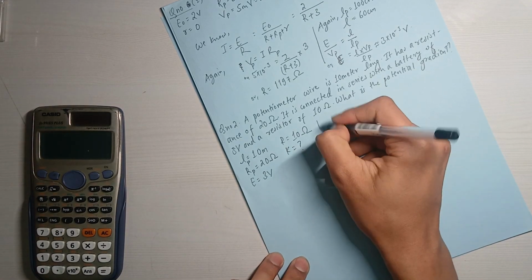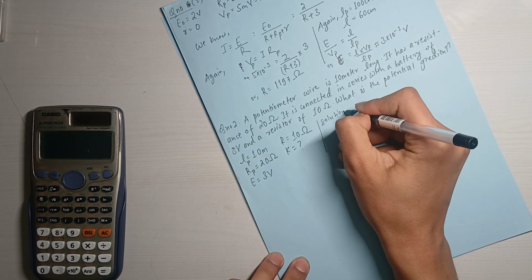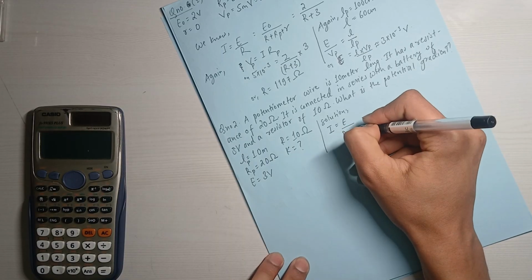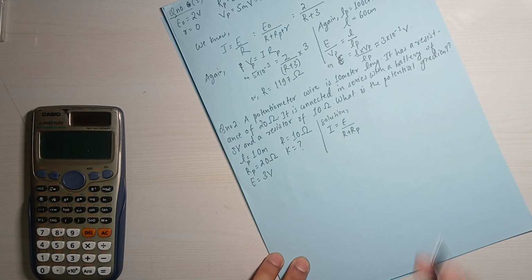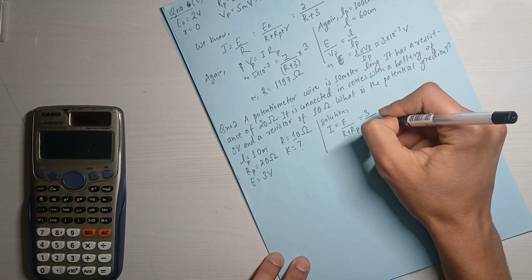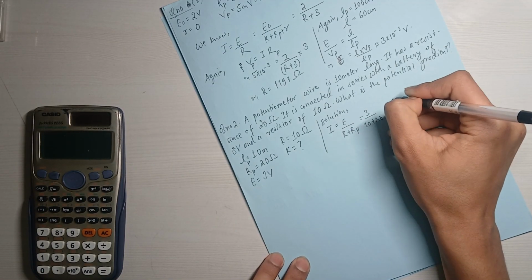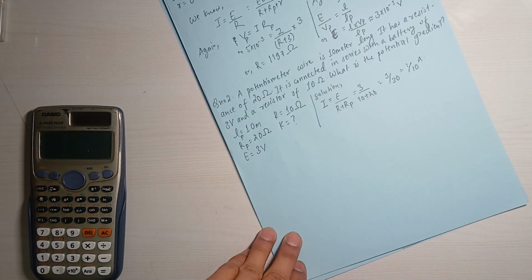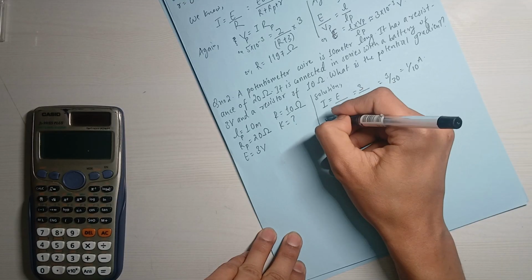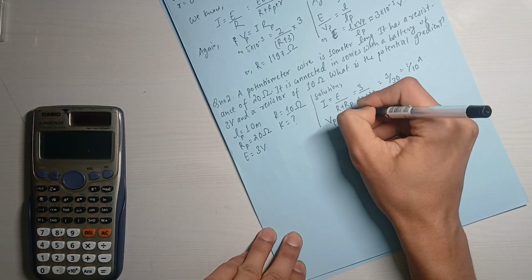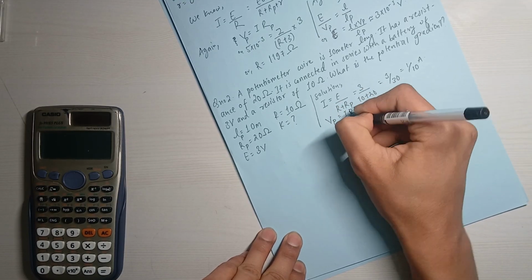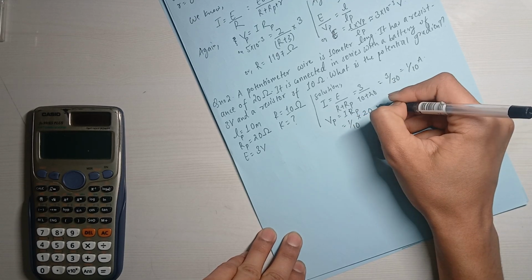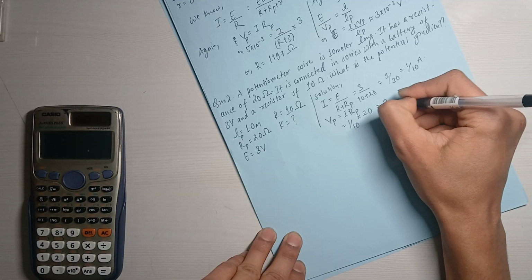This is a very simple question. You can just use the same thing we did last time. First, calculate the current by doing R plus RP, because internal resistance is not given here. So 3 by 10 plus 20, that is 3 by 30, that is 1 by 10 ampere. Now that we have I, we can easily calculate Vp, the potentiometer voltage: 1 by 10 into 20, which is 2 volts.